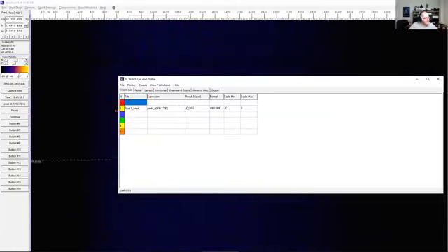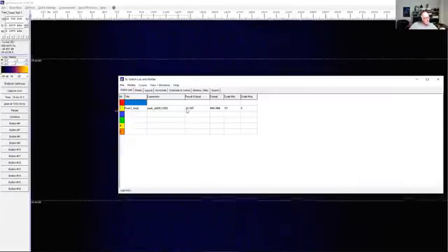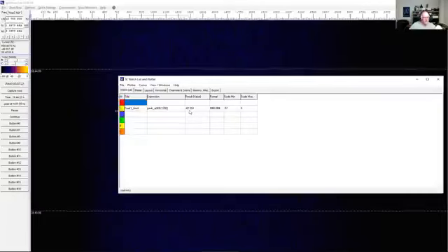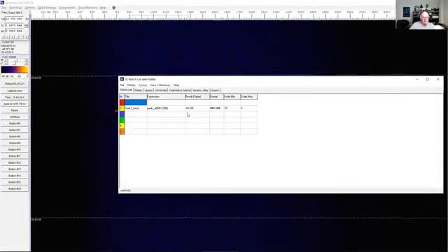Now, when it gets a big signal, this goes down a long way, or if you like, up a long way in terms of a plot. So it's detected a signal. So what you can do is write some code, and if you see a signal which is above, say, minus 50 dB, call that a meteor and then start to count.